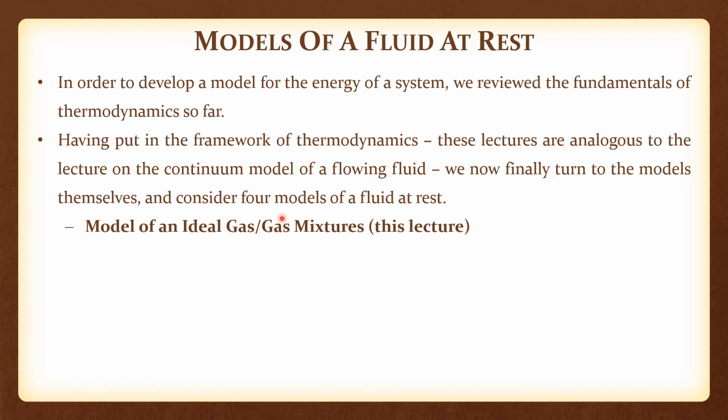One is a model of an ideal gas and ideal gas mixtures. This will be a two-part lecture. The first part of the lecture would be on the model of an ideal gas, and then the second part would be on ideal gas mixtures. And as you know, to get a little bit ahead of myself, ideal gases are gases where molecules have no form of interaction with each other. In other words, there is no potential energy of interaction.